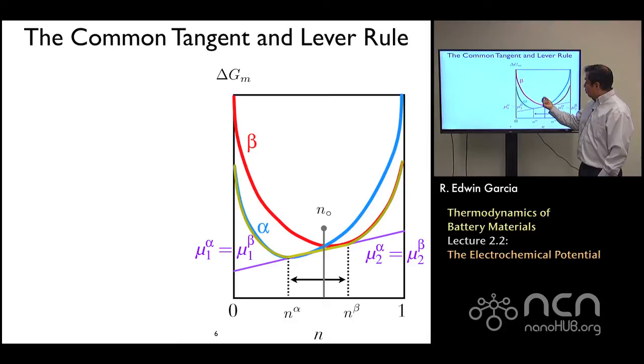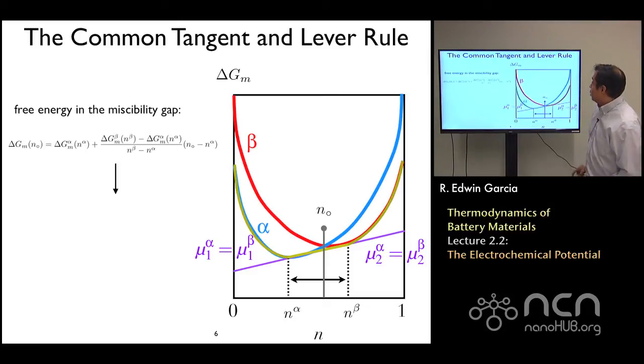Okay, when you specify that concentration, a fraction of the material will be more stable in alpha, and a fraction of the material will be more stable in beta. Okay, and what fractions will be which will be determined by the free energy as it's described here. And for that we really can specify what that free energy is by calculating the equation of the line.